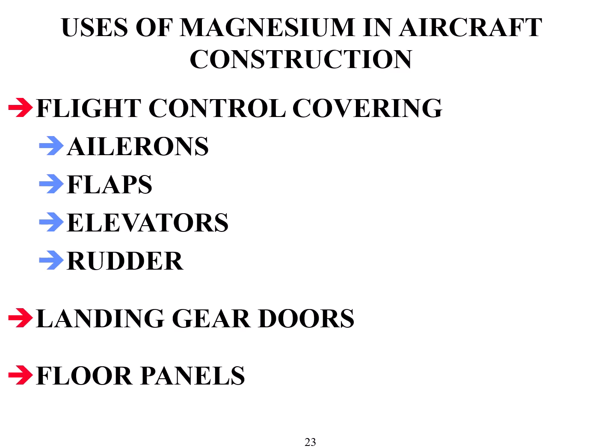Where would a magnesium alloy be utilized since it is more difficult to keep up? Often it was used in flight controls. As composites have come on the scene, they've replaced magnesium because they have the strength to weight that magnesium could produce as an alloy, but they don't have the negative corrosion characteristics.